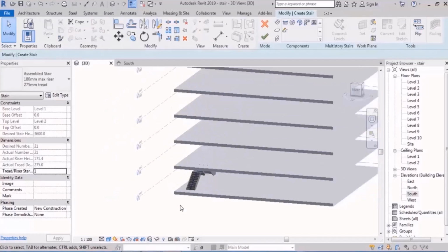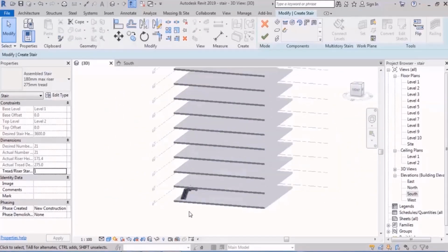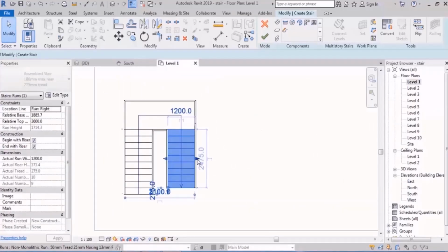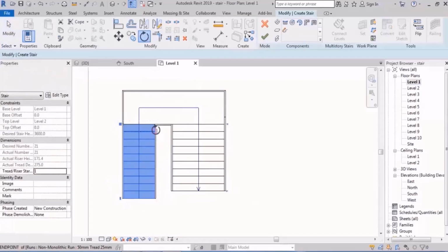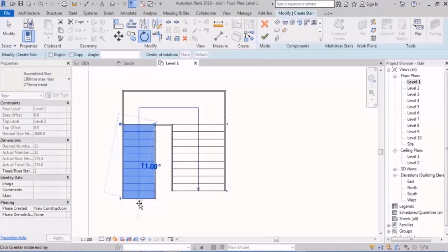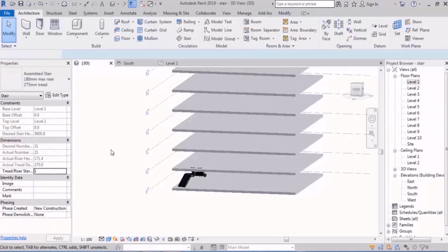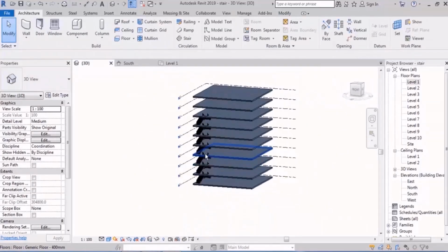The good thing about this is that when you click on edit stairs, every other staircases will be put aside and you can do your editing on that single staircase, for example this way. And when you click on finish, everything we have changed about that staircase, all the changes will be transferred to the rest of the staircases too.